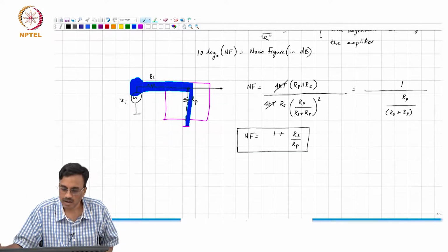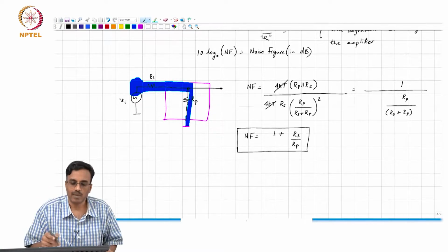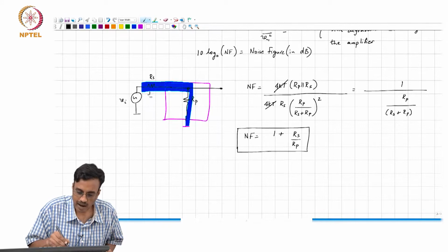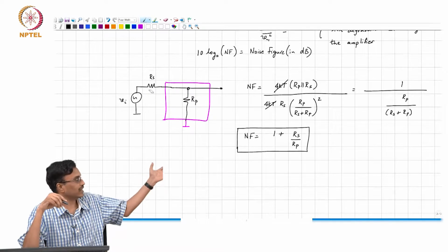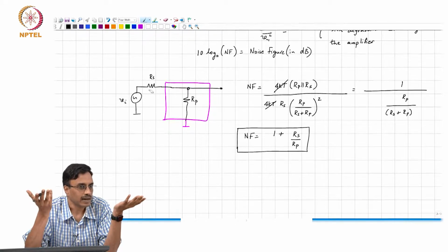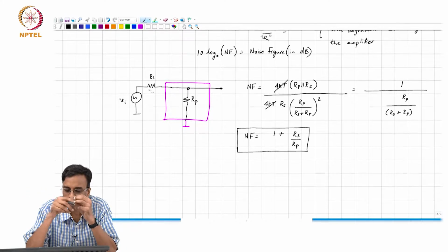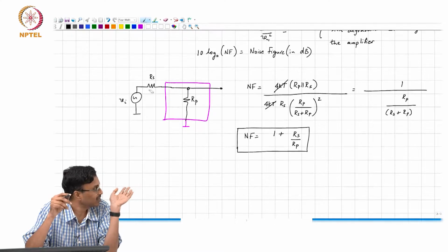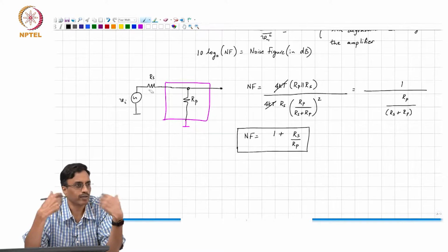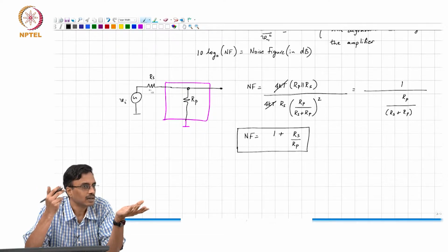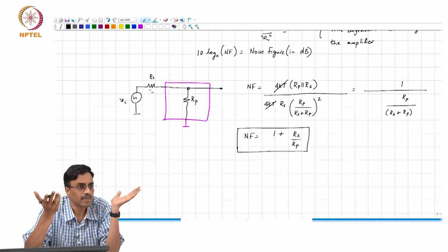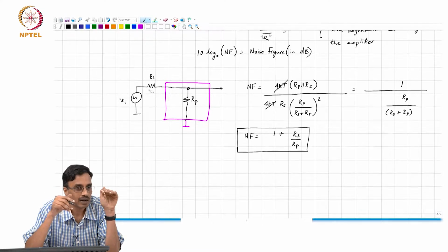We said this is our amplifier, so to speak, but what you are actually doing is attenuating, correct. Okay. So, if you simply attenuate with the resistive attenuator, as you can see, you are going to be degrading the SNR, right, okay.